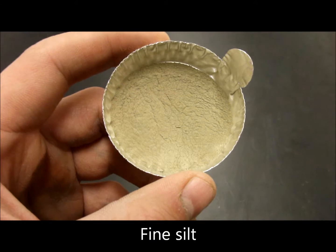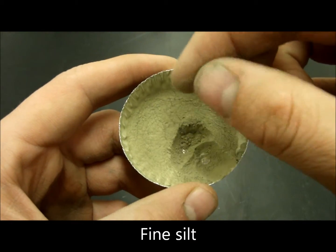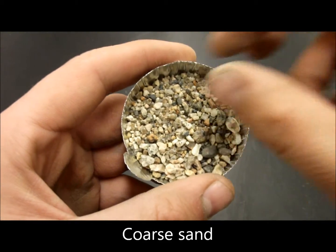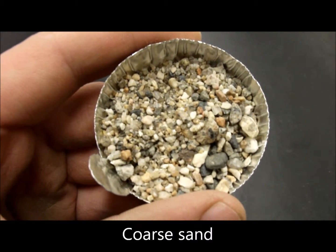Procedure. Preliminary classification can first be used to determine if a soil is coarse or fine-grained. Using sight and touch, approximate the percentage of fines in the soil. If the soil contains more than 50% fines, it is considered fine-grained, either a silt or a clay, and can be further identified through quick ID tests.